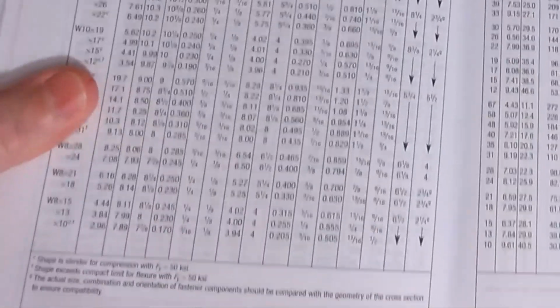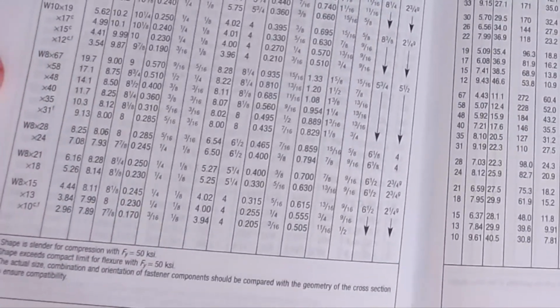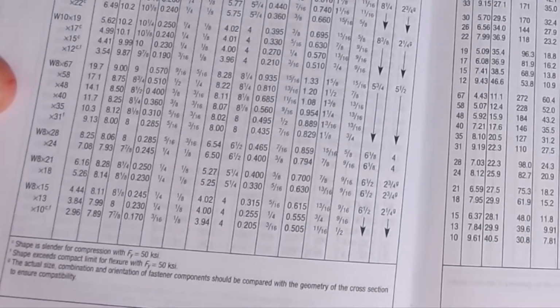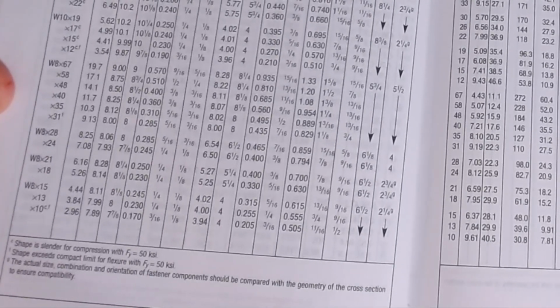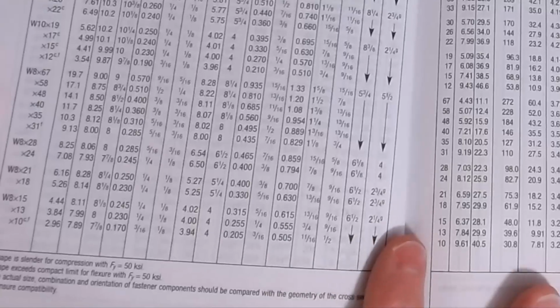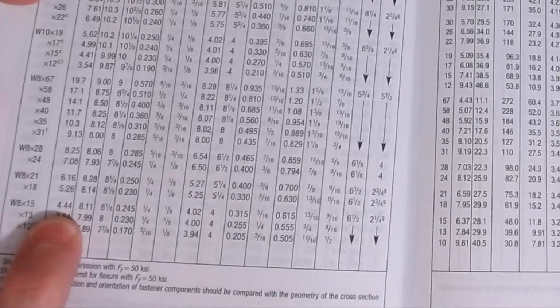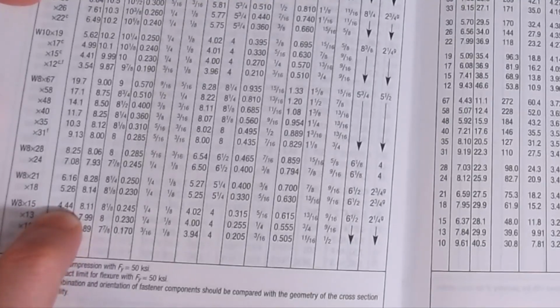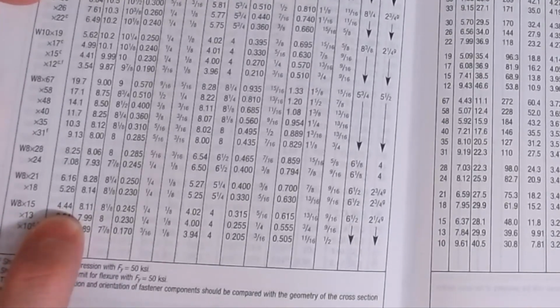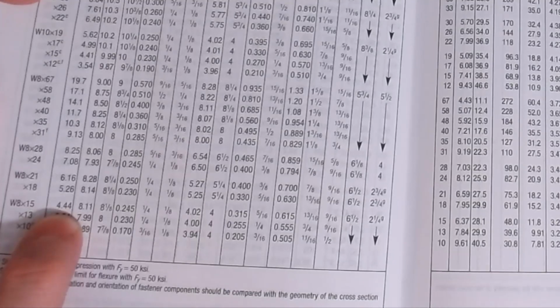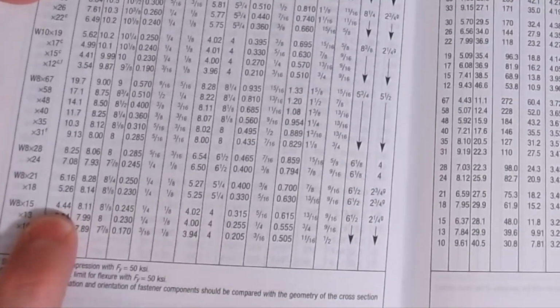what we can see is we're looking for an area that is 4.4 inches squared or larger, and an R minimum of 0.8 or larger. So if we look, one of the ones that leaps out at me is an 8x15, and that's just a fluke. I managed to hit one with exactly that area. I might be a little hesitant to use it, but for now, just for the sake of this exercise, let's say, okay, let's try an 8x15.